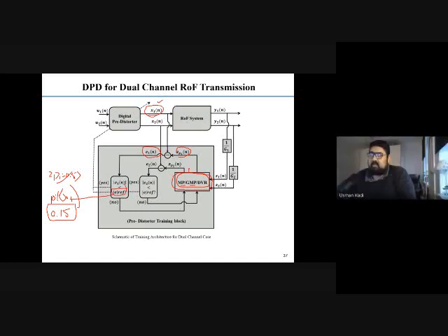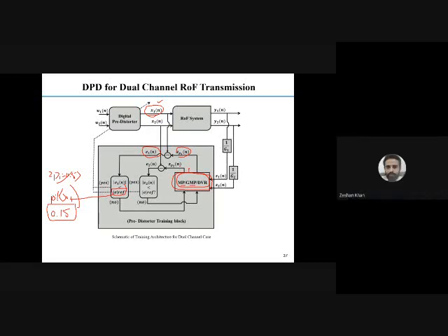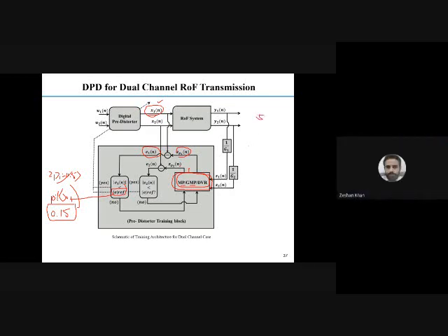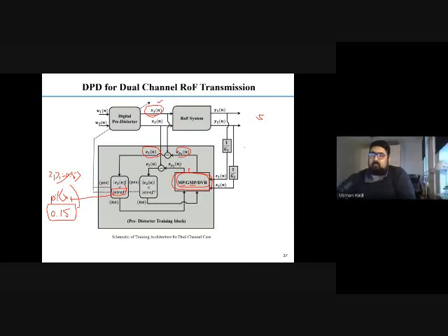So these general gain adjustments are done according to the floor of the signal that you have at the input. So they always change. If you're using 5 dBm of RF input power, maybe they are using 1 dB of gain adjustment. If you are at -10, maybe it is -15. So they are automatically adjusted with the help of the input signal floor that you get from the signal generator.